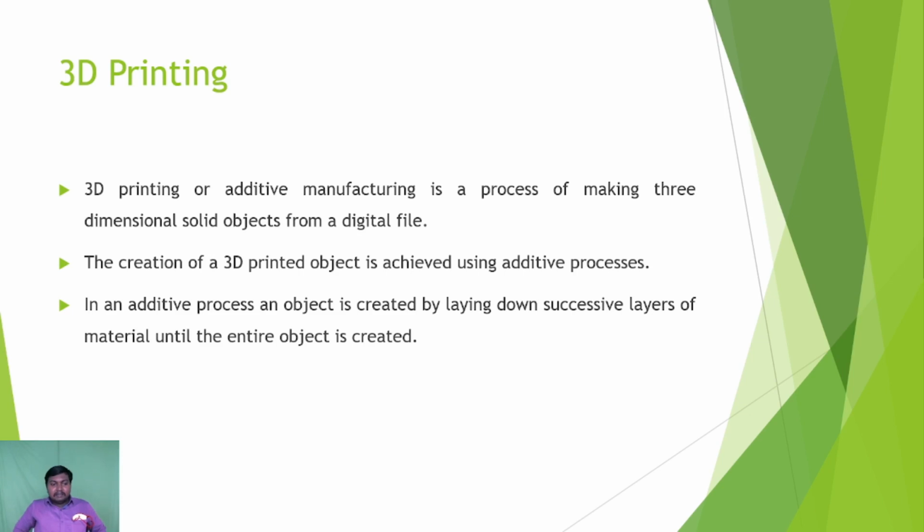Second, there are three types of manufacturing processes. First one is subtractive manufacturing. Commonly, we are using subtractive manufacturing. In lathe or drilling, we are using subtractive manufacturing. We are removing material from the existing part. It is called subtractive manufacturing. Same like that, in 3D printing, we are depending on additive manufacturing. We are adding layer by layer and finalizing the 3D part, which is called 3D printing. And another one is the formative process. Bending and forging all come under the formative process.